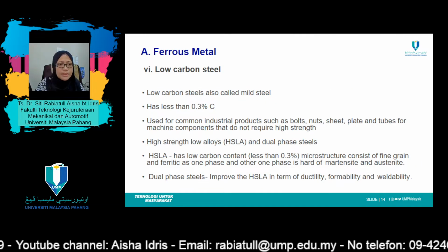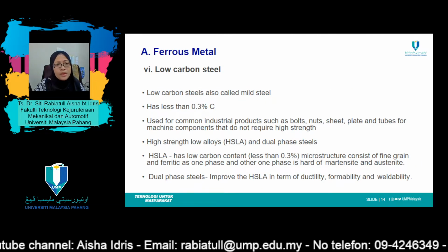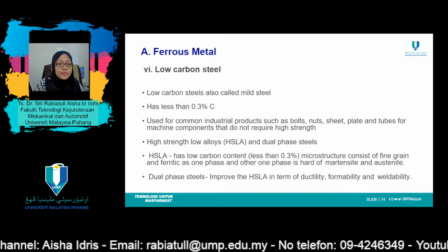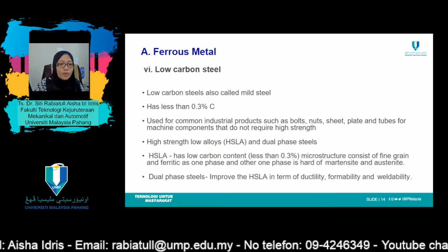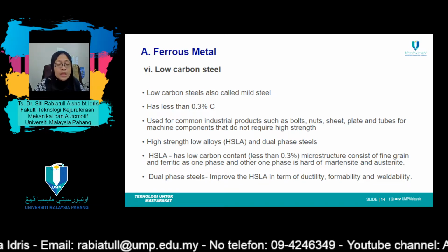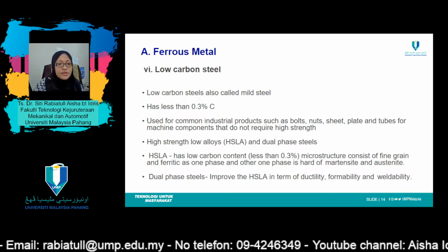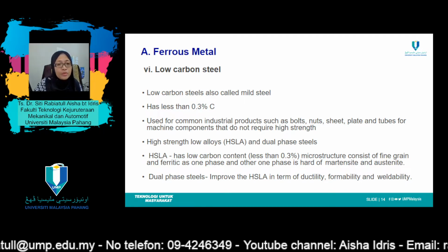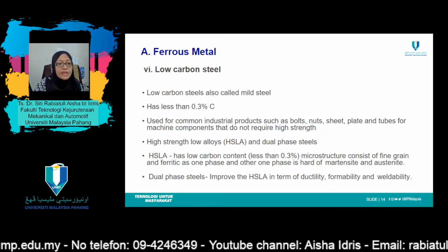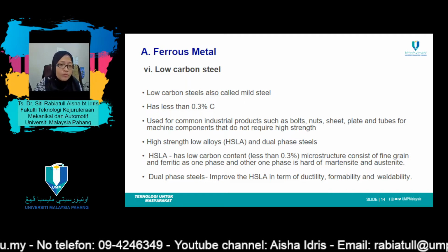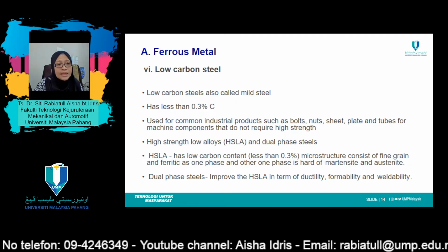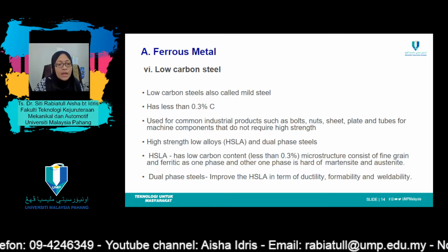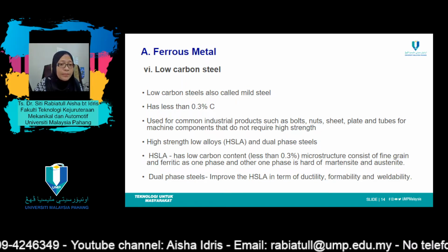For low carbon steel, of all the different steels, those produced in the greatest quantities fall within the low carbon classification. These generally contain less than about 0.25% carbon and are unresponsive to heat treatments intended to form martensite. Strengthening is accomplished by cold work. The microstructure consists of ferrite and pearlite constituents.